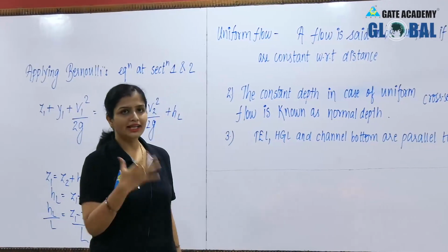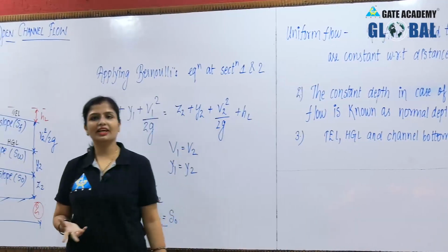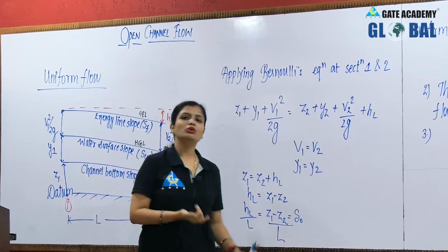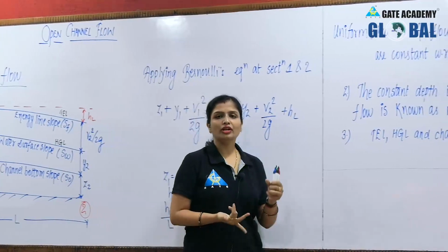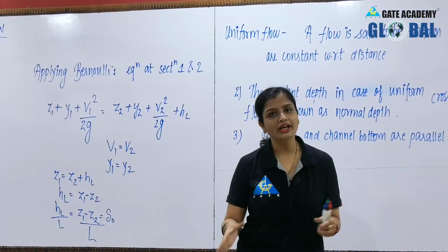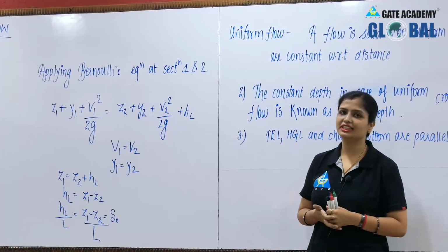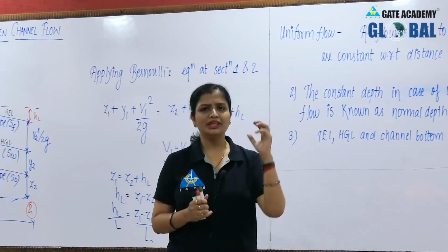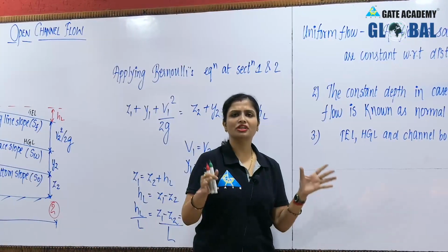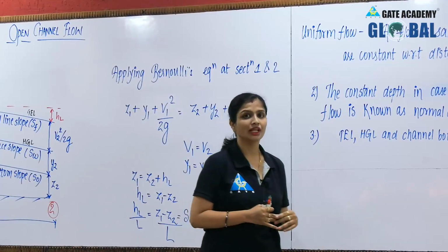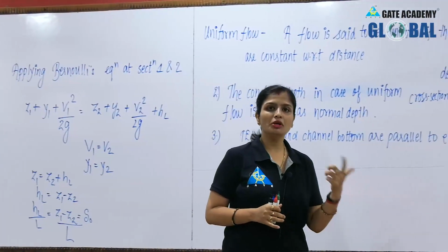At least I need any two parameters, like discharge is equal to area into velocity. If I know the discharge and the velocity, I can calculate the exact area of the channel section to be designed. So basically you will know the discharge, a certain Qmax coming in that particular channel section. But how to calculate the velocity?